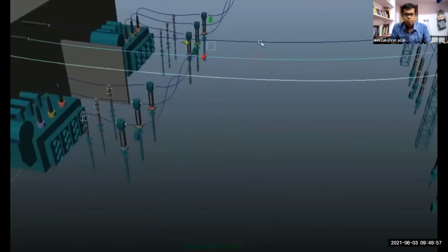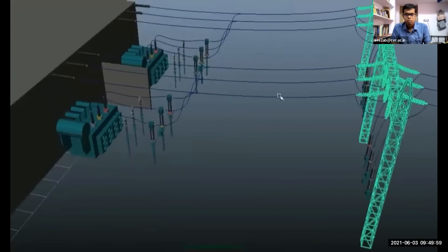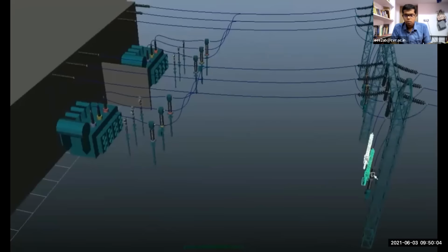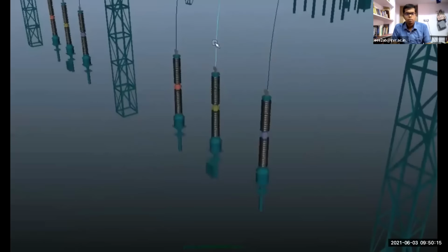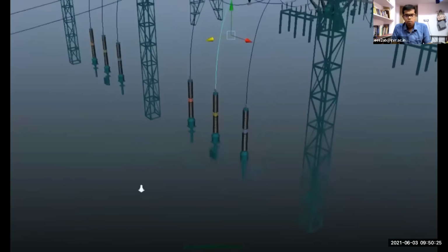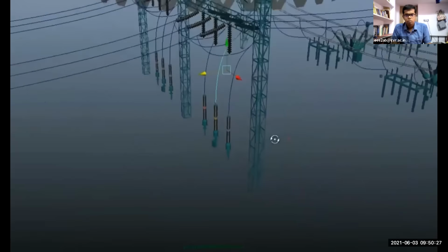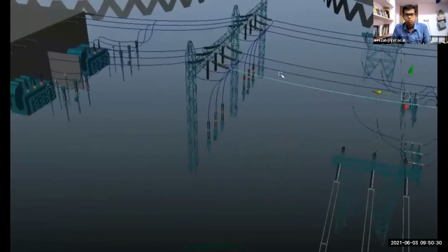In the line it could be measured. After that, these conductors reach the gantry. Voltage transformers are installed here to measure how much voltage is on the line conductor. These look like current transformers, but they are connected in parallel to the line conductor. One terminal is connected to the line terminal while the other is connected to the earth. In the secondary circuit of each transformer, a voltmeter is connected so that we get regular information of the voltage of each phase.